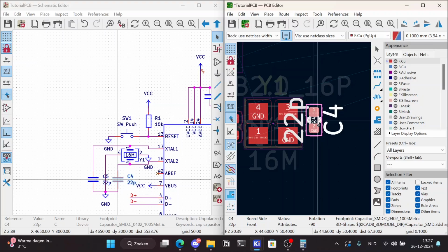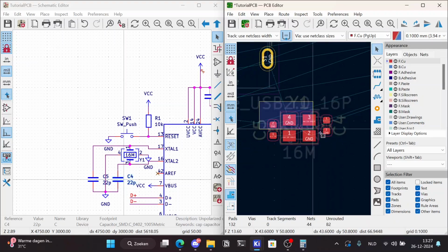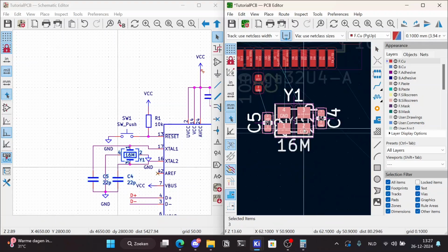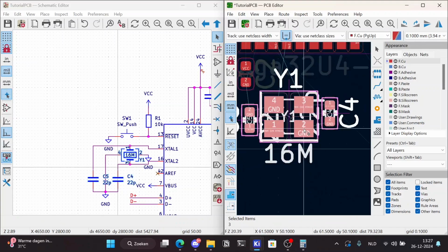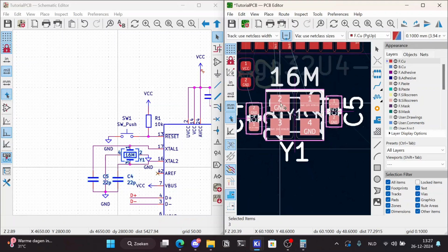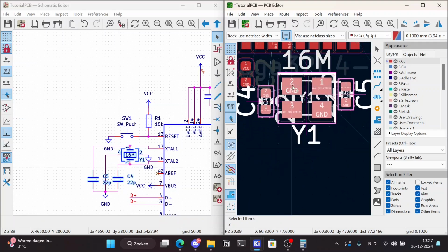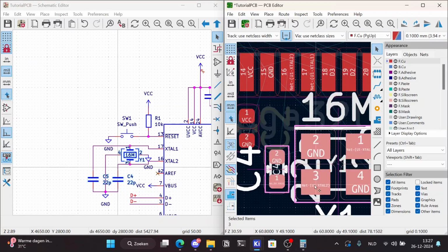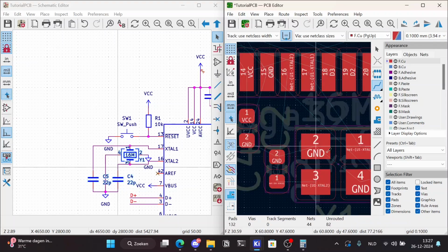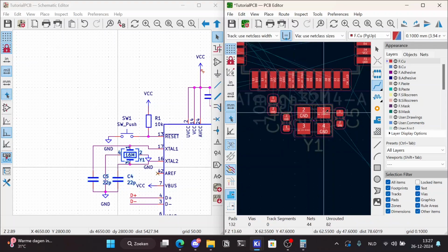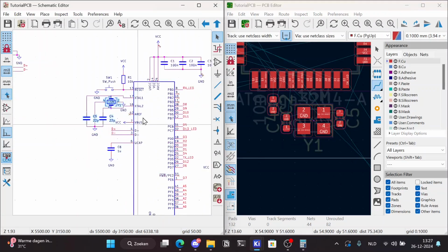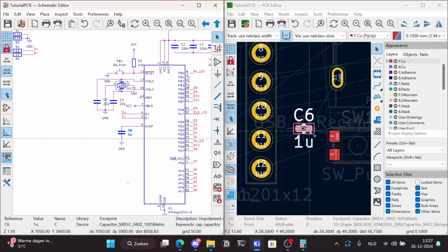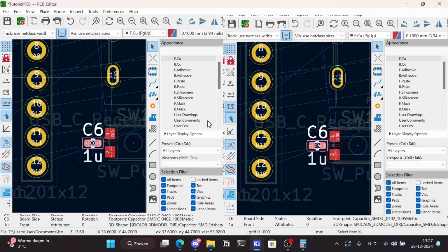So you have to at least 2 capacitors, and you have to make them line up with each other. As you can see, this does not line up, so you have to rotate again for them to line up. As you can see, XTL2 matches and XTL1 matches too. Great. Now we can actually start doing our actual layout.